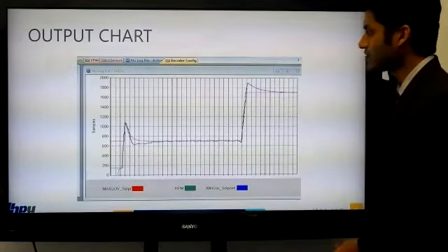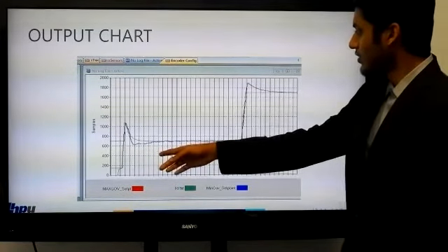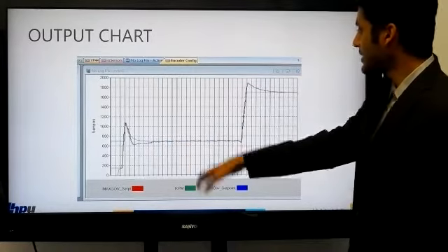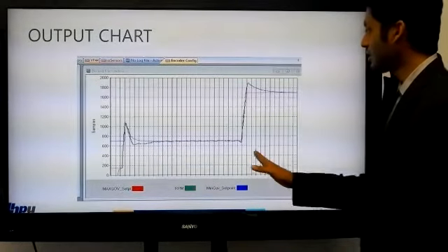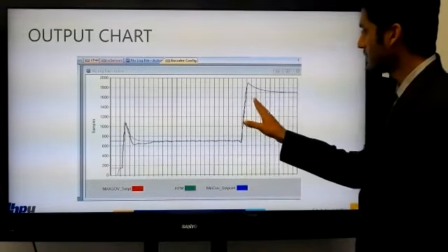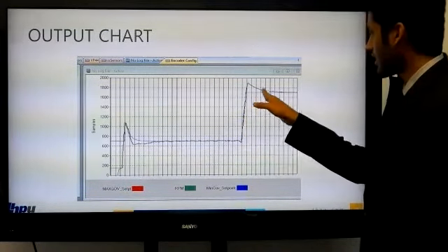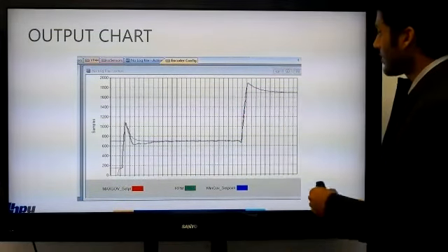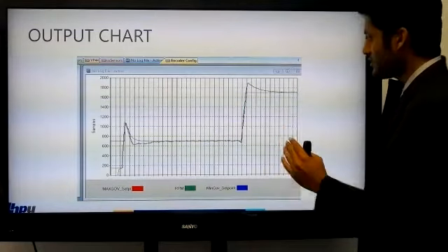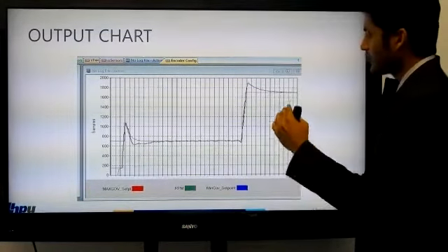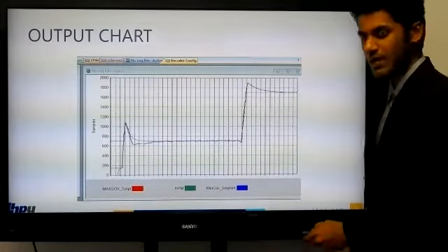So this is our output chart. When we started the engine, it was working fine since we calibrated the P and I gains of min-gov. But when we suddenly gave the full throttle, it just reached beyond 1700 and matched with the desired RPM. But when we gradually give the pedal as in real life conditions, it would smoothly go and reach our maximum power.